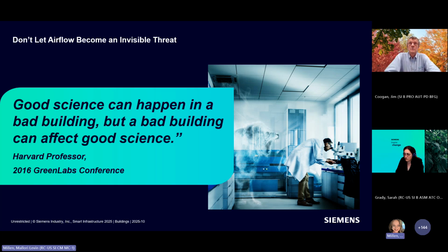Okay. For hood flow reduction, why not consider converting traditional fume hoods to high performance fume hoods that can reduce flow by up to 40% for both CAV and VAV fume hoods? That's a good idea. I wouldn't, he asked why not, I would say, definitely consider that. Fume hoods have gotten better over the years, partly as a result of a good test criteria, a good test protocol. A lot of you are aware that ASHRAE has a fume hood test protocol that measures performance in several ways, including tracer gas containment test.